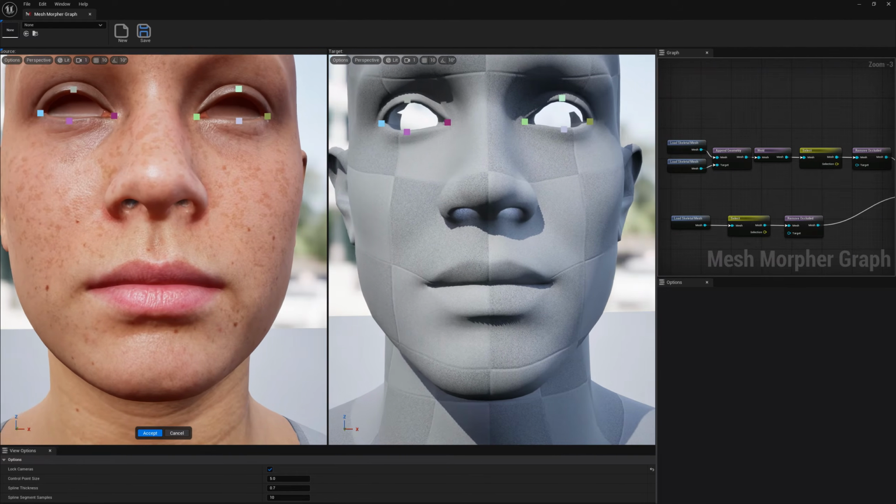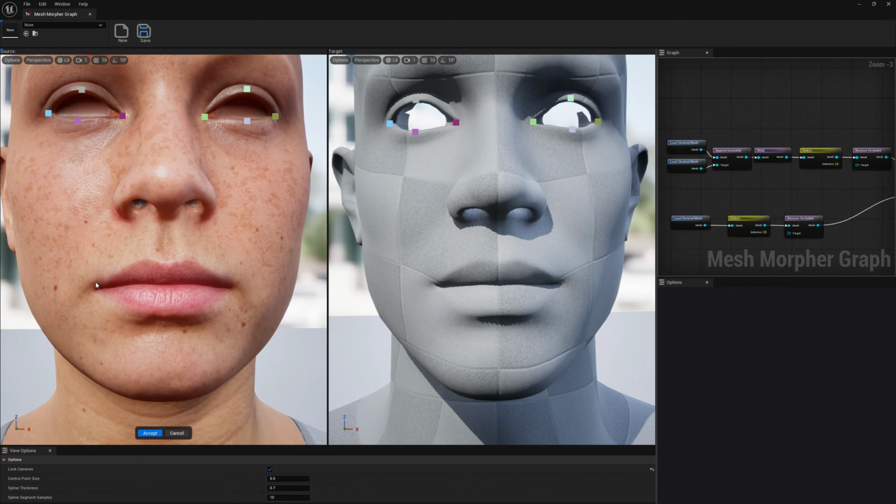So let's go ahead and start a spline landmark, and to do that we press T, and we will have this small menu here. To cancel it, we just click cancel or escape, and to accept it, you either press again T or accept the changes. Let me show you. So to accept the spline, you click on finish spline or T again, right?